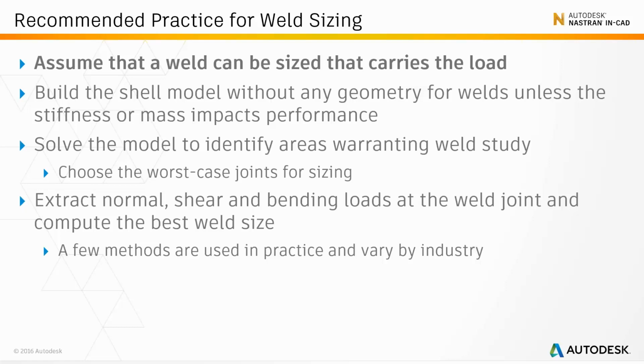So they're really the two key considerations for whether you include your weld beads in your analysis: one, whether it adds stiffness to your design, and two, whether the mass of your beads is going to affect the dynamic or inertial loads of your design. Most times though, welded structures are many times the magnitude in size of the weld bead itself, and so leaving it out is not going to make a significant difference in the global response of your product.